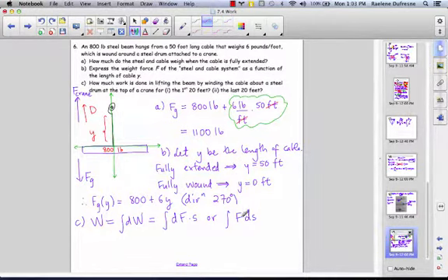And so we will not be using the dF version of the work calculation. So we have the weight is F, or 800 plus 6y. The displacement is going to be dy, a change in y. And the only other thing we need to concern ourselves with are the bounds of integration, the values for y for the first 20 feet.